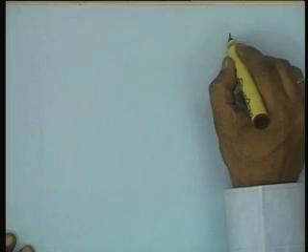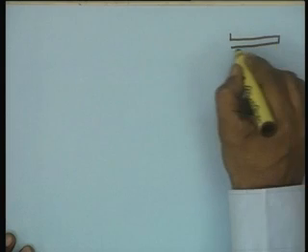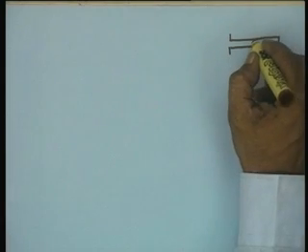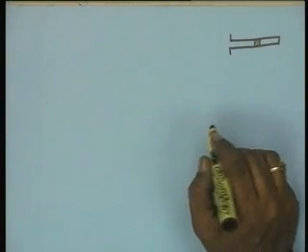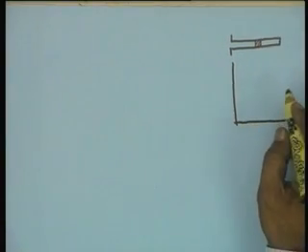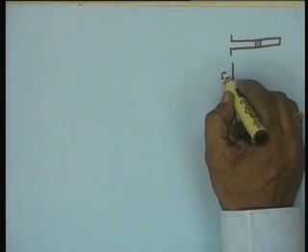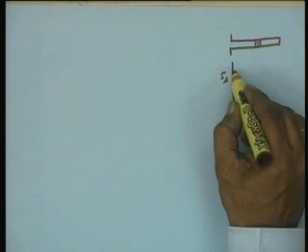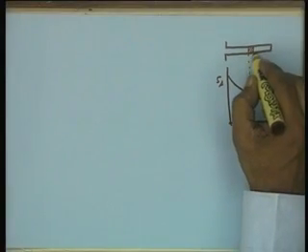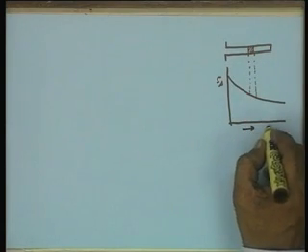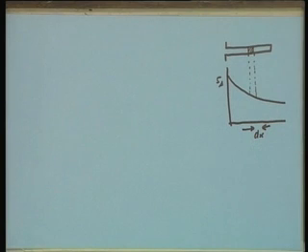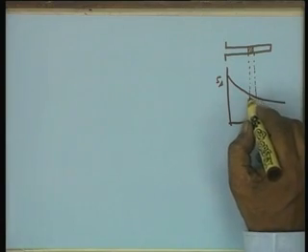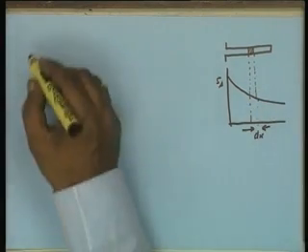Let us say we assume in a very simplistic way that the enzyme is taking place in a cylindrical pore, and now consider a small differential element in this pore, along which the mass balance can be made. Let us say this is your Ss, the substrate concentration at the surface, and this goes down across the pore. Let us say this is your dx, the length of the differential element, and now we make a mass balance across this differential element at steady state.